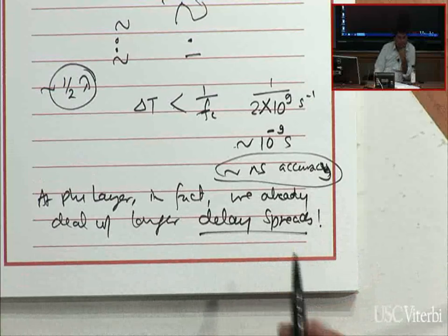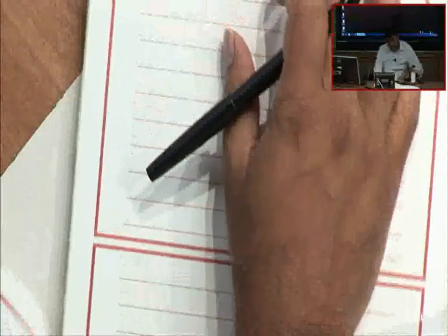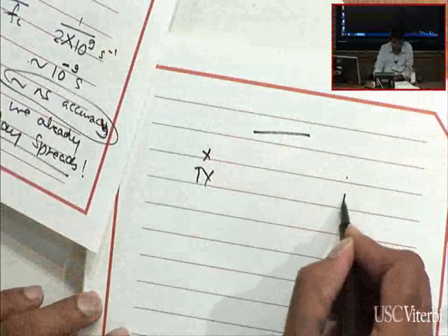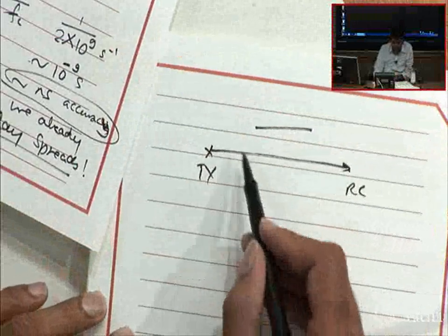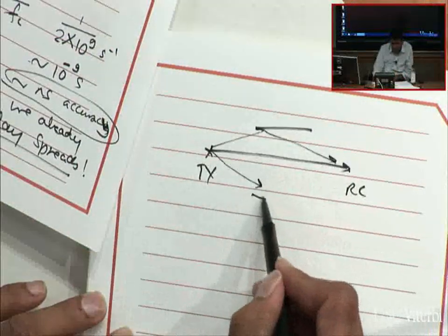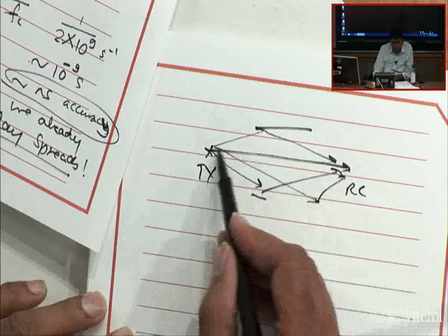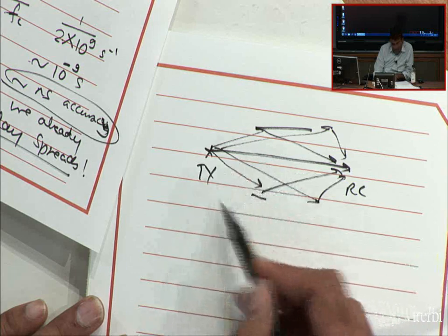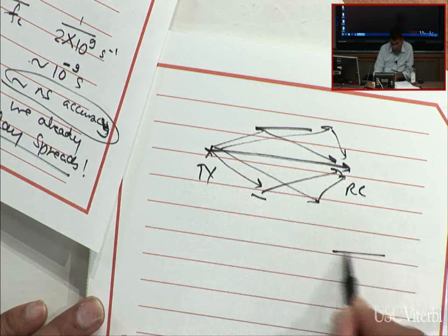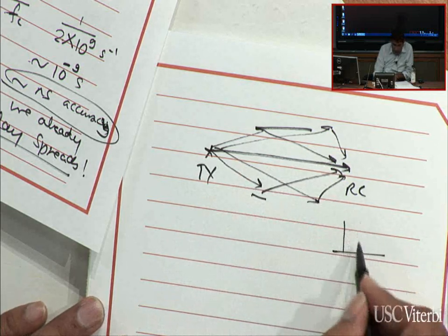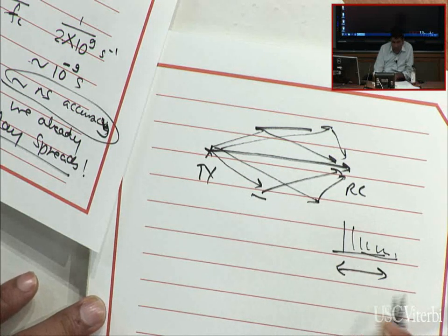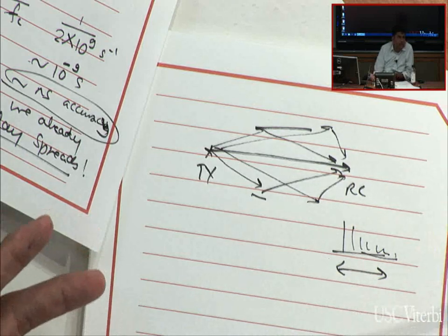Okay. What is delay spread? If you remember from our earlier discussion about the physical layer, your packet from the transmitter to the receiver is typically not just a direct signal, but a bunch of reflected signals from different components, right? So each of these components traverse slightly different distances. And when you took all of those into account, what you got at the receiver was the line of sight signal showing up at a particular time, but maybe a bunch of other signals show up at later times. And that time span over which they showed up, that is called the delay spread.